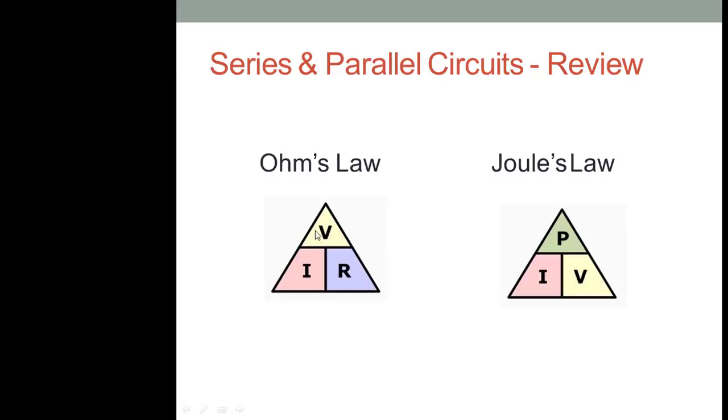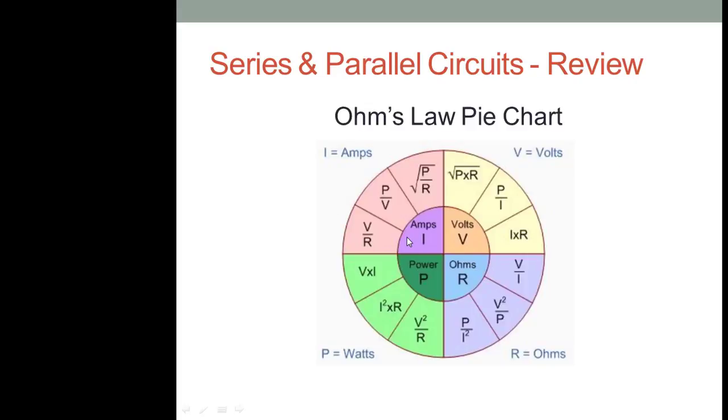And again, you remember these visuals. This is just kind of a help in calculating both Ohm's law and Joule's law. All you need to do is cover up the one that you're looking for, and you can see what you need to do with the other 2 components, if you need to multiply or you need to divide. And then this is just a pie chart taking the 2 equations and using substitutions, the different ways that you can calculate the amps, the volts, the ohms, and the watts.